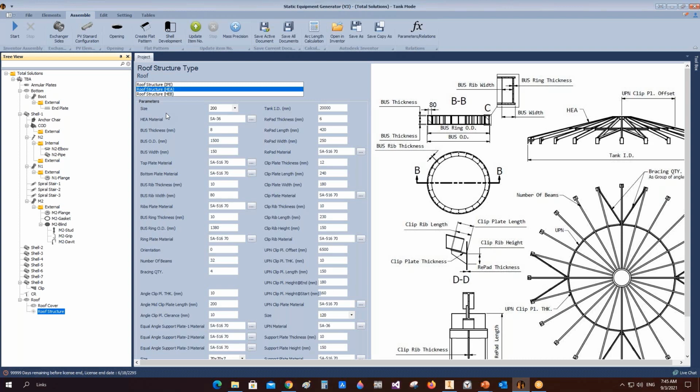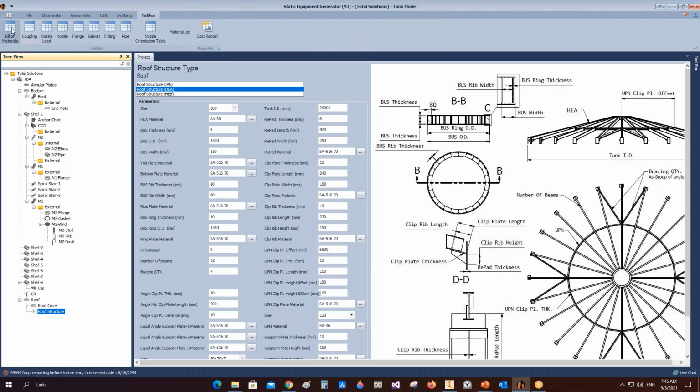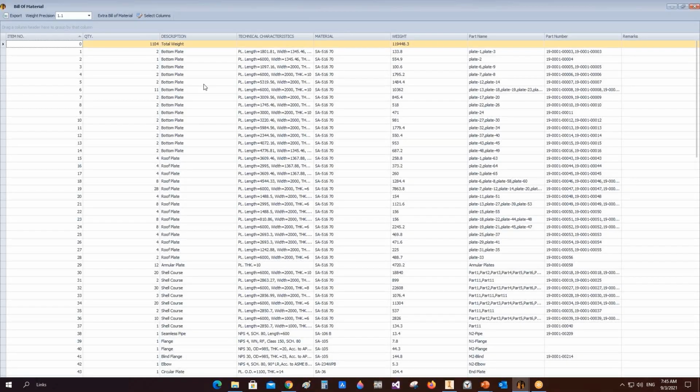Okay. So one more question for storage tank, and I think that is the last question for storage tank. Plate cutting diagram. We need a plate cutting drawing to issue to the site for the cutting of the plate. Whether it gives us the plate cutting drawing, showing the number of plates required to build this tank. Yes, sure. Here, nesting of the plate, basically.